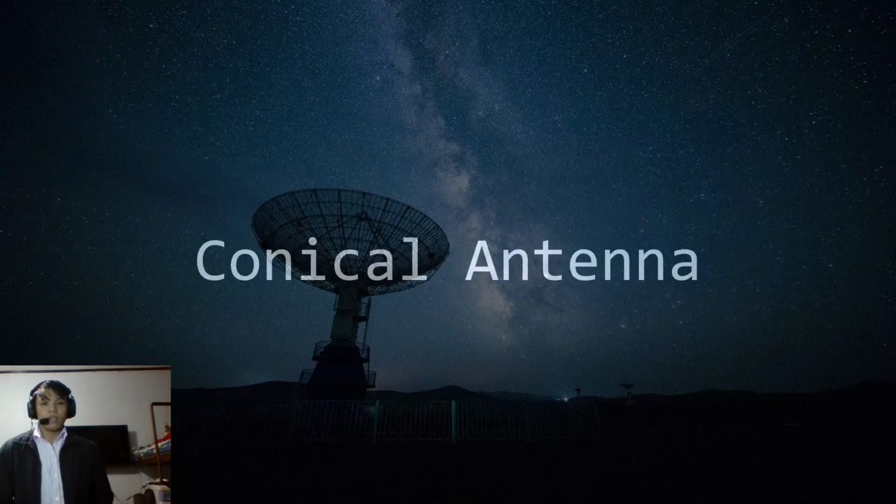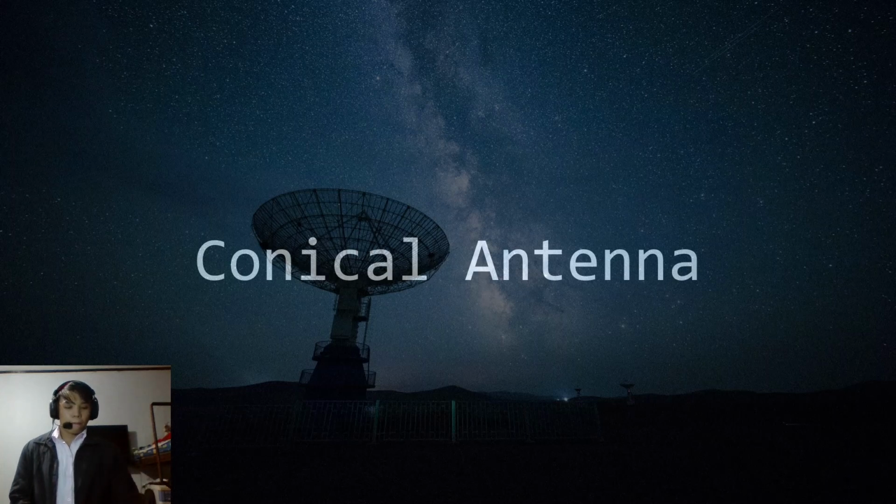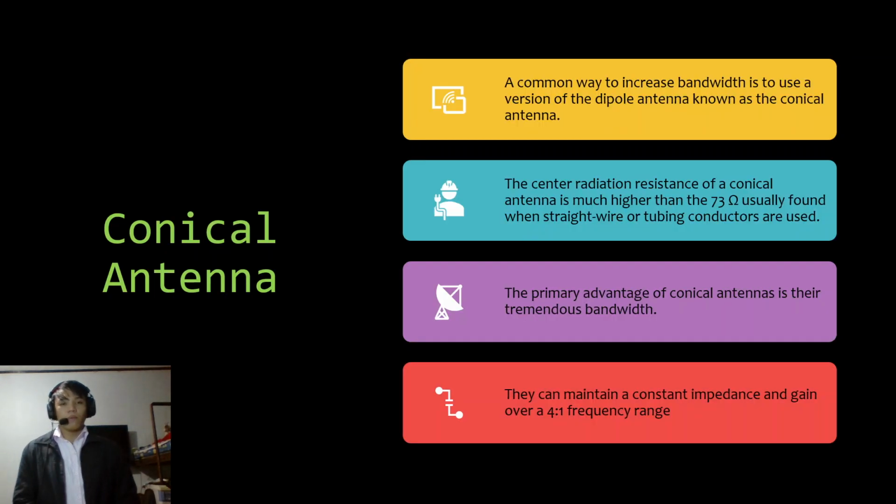Next is the conical antenna. A common way to increase bandwidth is to use a version of the dipole antenna known as the conical antenna. The center radiation resistance of a conical antenna is much higher than the 73 ohms usually found when straight wire or tubing conductors are used.